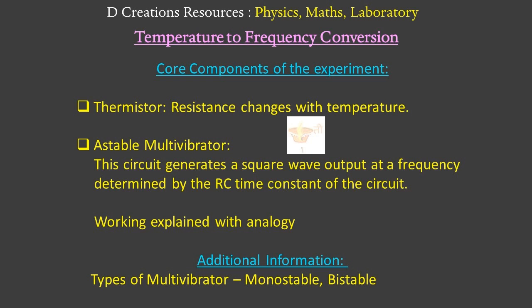But then it returns to the stable state on its own after a set time. But in case of bistable multivibrator, it requires an external trigger to switch between both the states. So it's also called a flip-flop or latch in digital circuits.